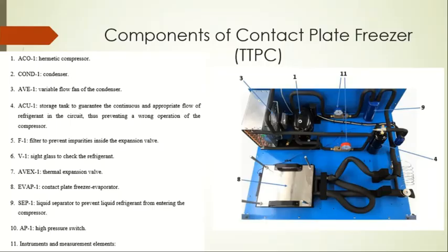So similar here, if the liquid part enters the gaseous part, definitely it causes certain hammering formation and disorderliness of the process, which is normally known as the surging phenomenon. So to avoid that, this separator is installed, which ensures that the liquid retains its bottom position and the gas will move on and enter the suction of the compressor.